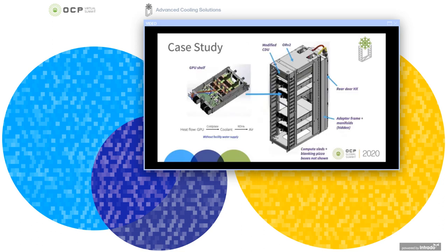As a preface to the air-assisted liquid cooling effort, the first step was conducting a case study to understand the true benefits of enabling closed-loop liquid cooling in an air-cooled facility. In this case, a very quick project involving liquid cooling GPU shelves in an Open Rack V2 was conducted. Here, the liquid cooling loop is created by the GPU shelves, or the cold plates in them, along with rack-level manifolds, a rear door heat exchanger, and a modified CDU to drive the coolant closed loop.